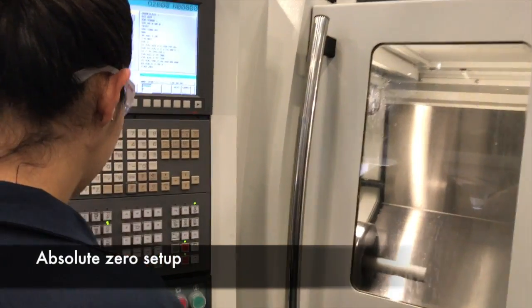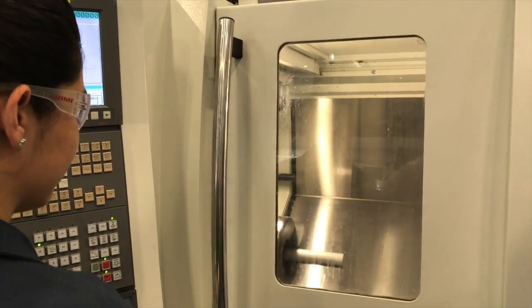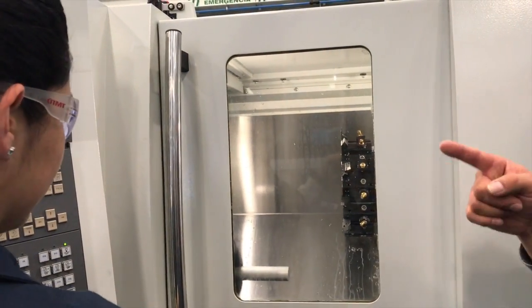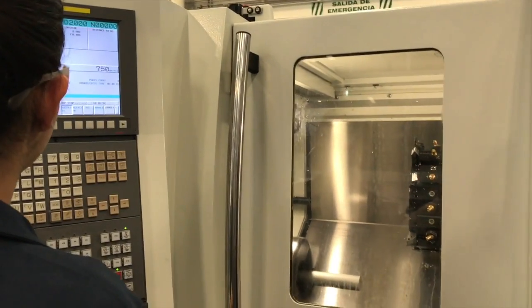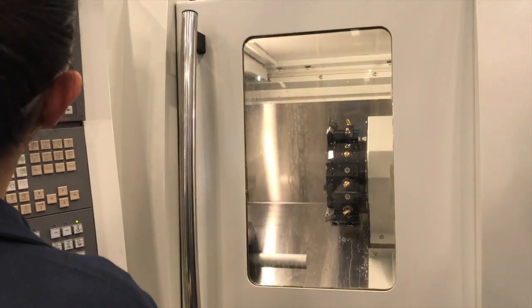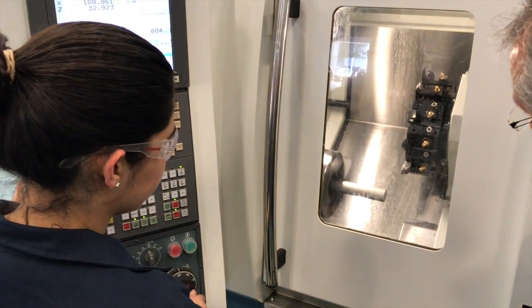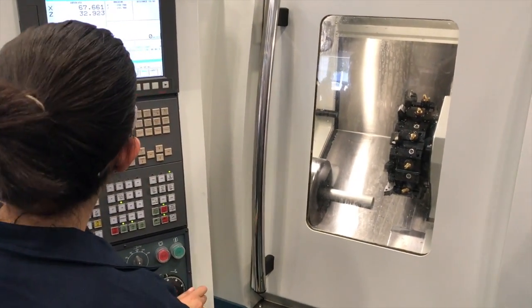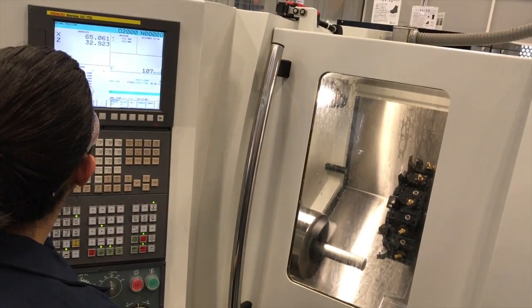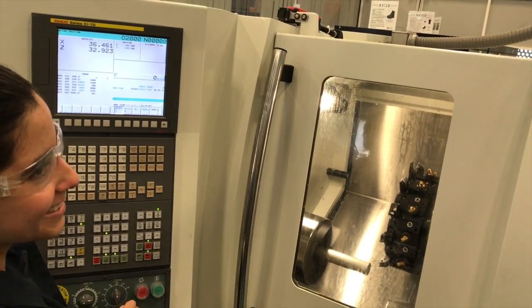Absolute zero setup. After sending the tool to home position, we have to use MDI operation mode to move the tool close enough to the outside diameter and the front face. It is very important to adjust the incremental position steps to control with more precision the motion in order to barely touch the front face. In our case, as our raw material has a diameter of 38.1 mm, we move in the x-axis up to the 36 mm. With this, we make sure we are just in front of the front face.